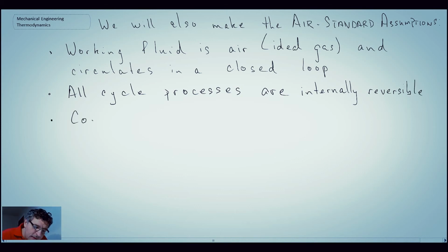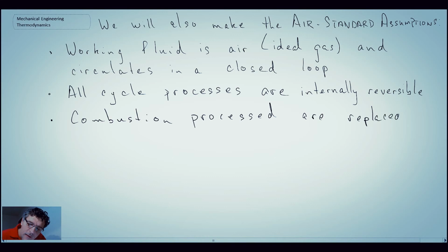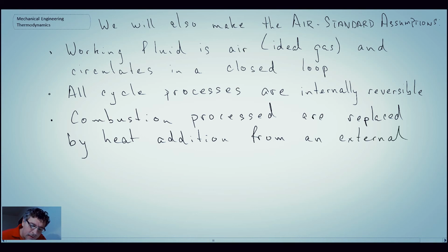Now, we do have combustion, but we're assuming the working fluid is air, and consequently we do not take into account with this air standard assumption that we have a fuel-air mixture. But what we'll assume is that combustion processes are replaced by a heat addition process. And we're going to assume that this is coming from an external source.